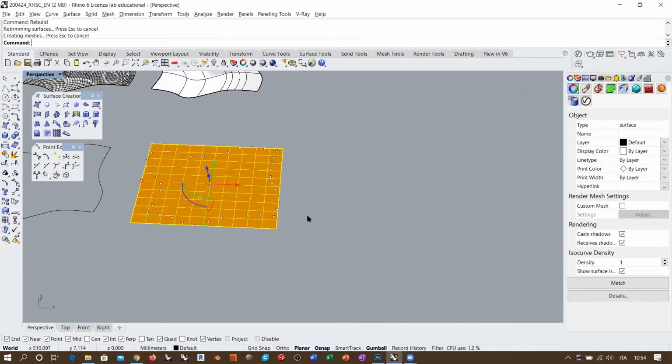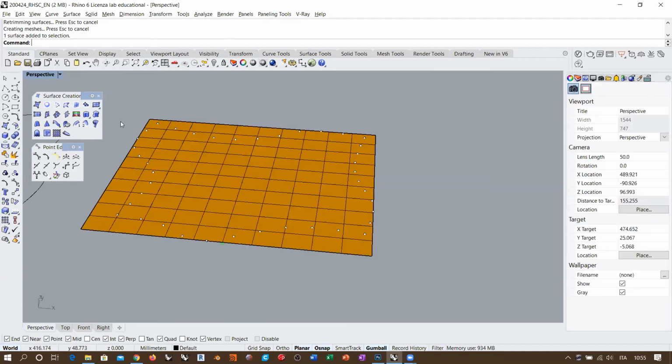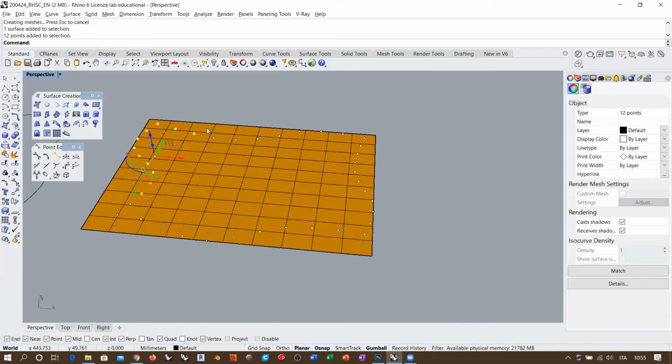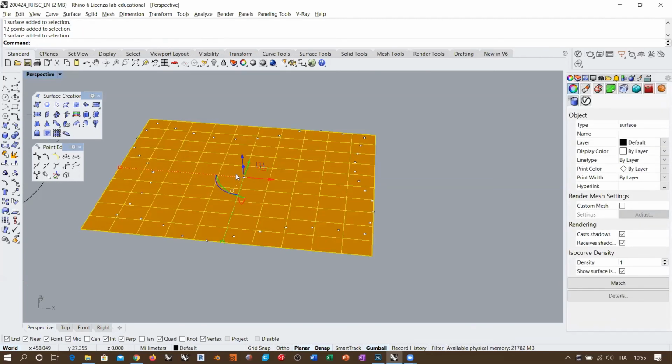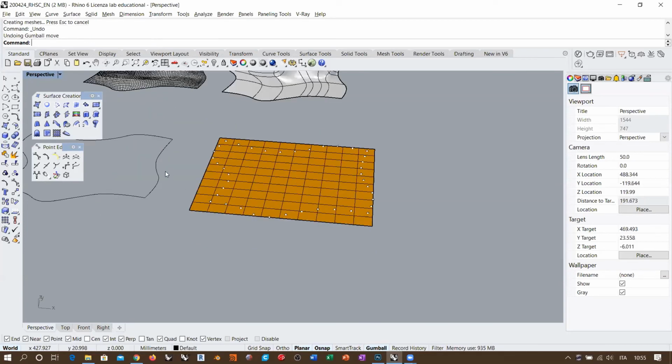Okay, so this is the fitting plane with a rebuild that the patch command is creating. And then if the patch detects that all these points here are not at the same height, it starts to take the control points of the surface and displace them in order to have the surface fitting, or passing more or less through the points derived from the input objects.